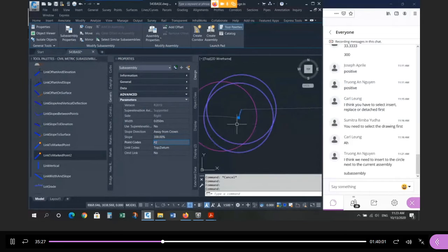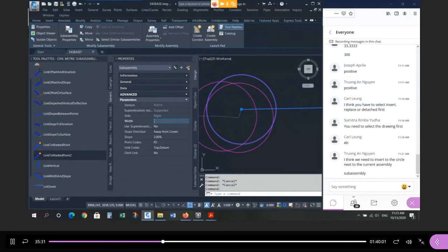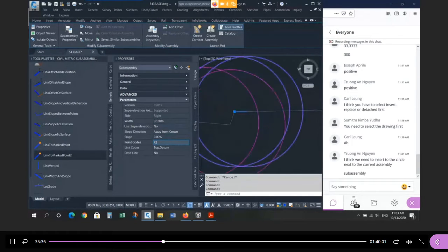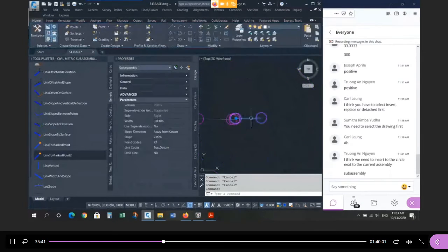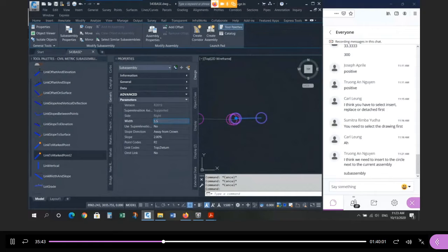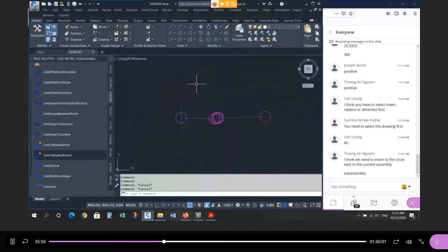So now you'll see the face of the curb. The next piece should be 0.15 wide, 0%. So there's the top front face of curb. So there are the 3 planes from your curb and gutter, these 3 pieces. And then the last piece should be 5.55 at positive 2%, which is the default. So there's your standard half of 20 meter right of way.